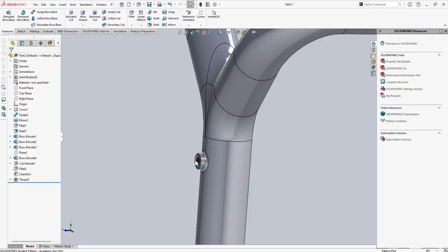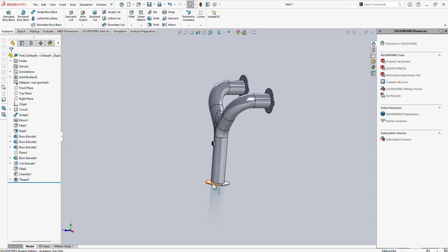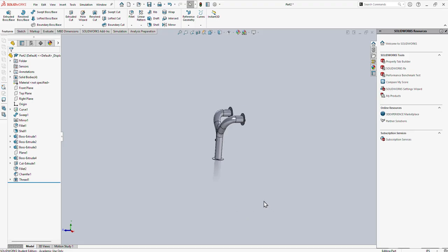It reads the exhaust coming out from the engine, and the computer of the car reads that, and then it goes through the catalytic converter, and then the flex tube, the other tubes, and it goes bending like this, all the way up there to the muffler.